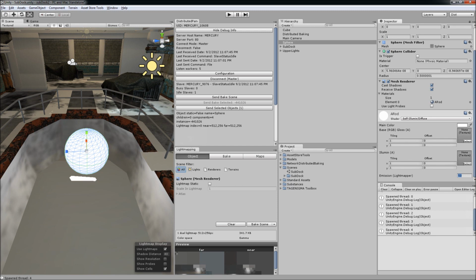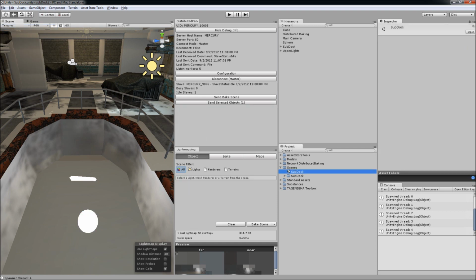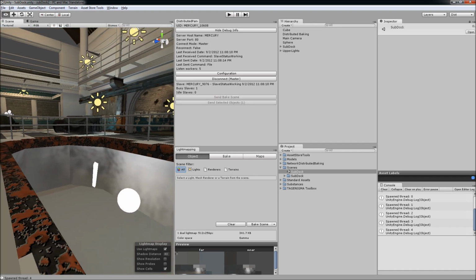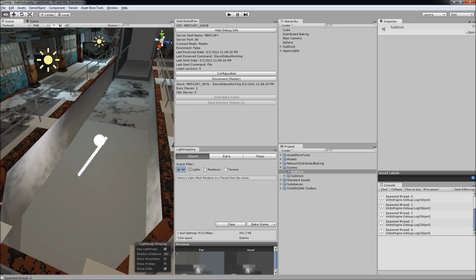So let's create another light source. It'll be a sphere. We assign the self-illuminated shader. The emission was 50. We'll change it to 75, a stronger light map. Reduce the scale of the source. Move it down. Change the position of the sphere to get an interesting light effect. Save the scene change.